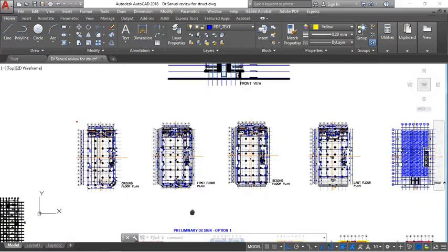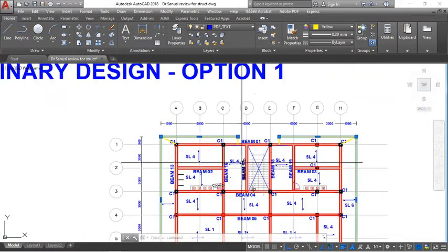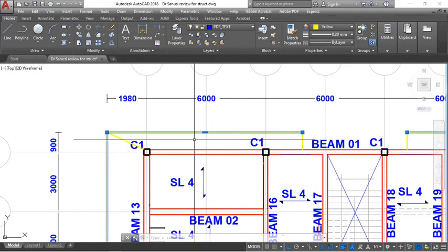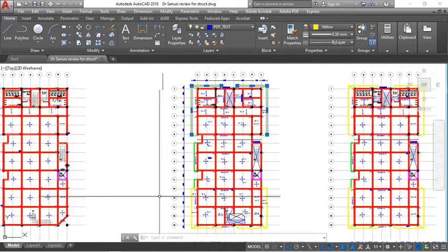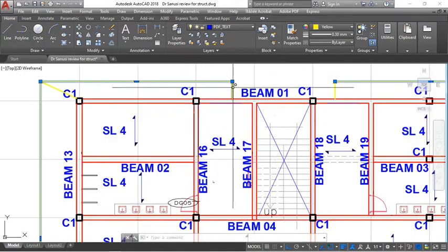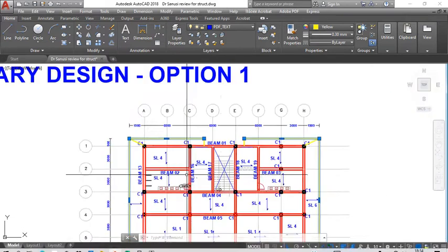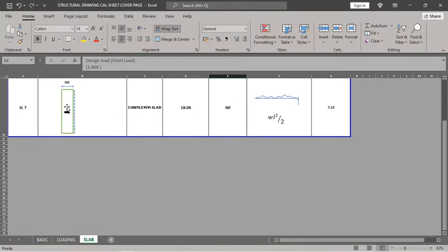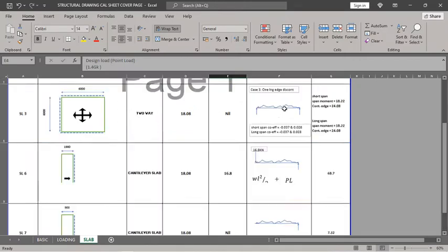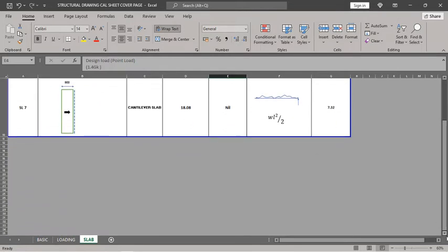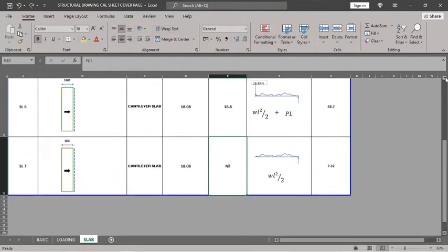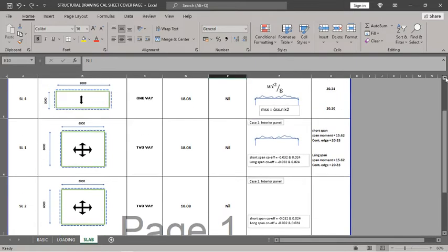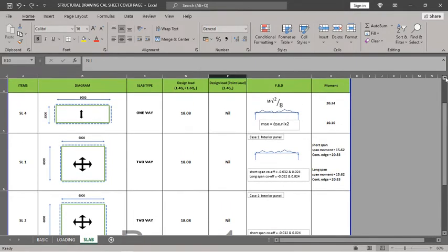So in my model, which is this, for the wall load, I've assumed that since I've factored the load, I didn't consider that because the effect will be negligible. So I did not put wall load on that slab. So that's why we have it here. That's why it's nil also in this case. Every other slab, I've assumed a partition wall allowance on all those slabs.